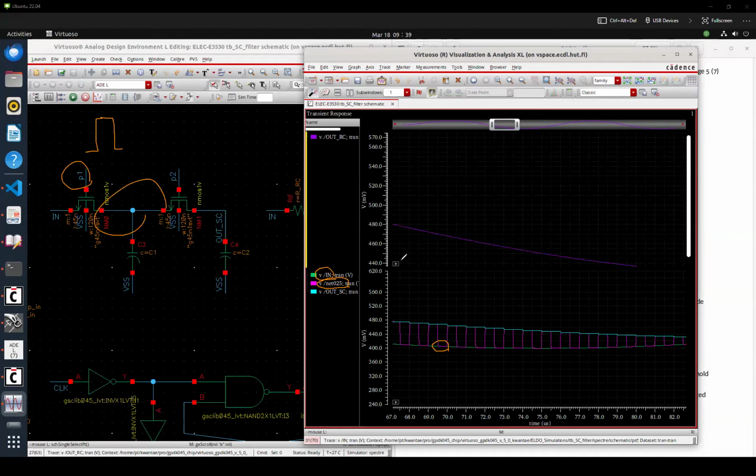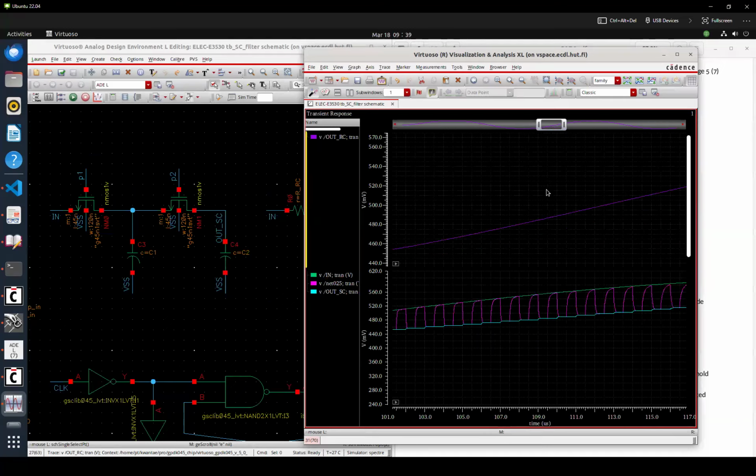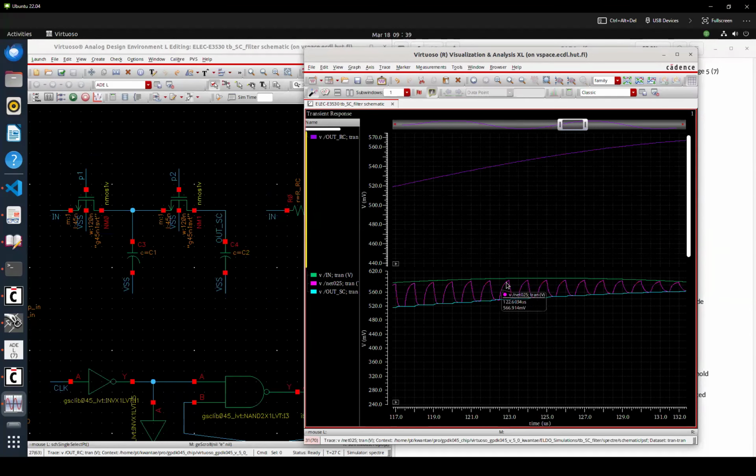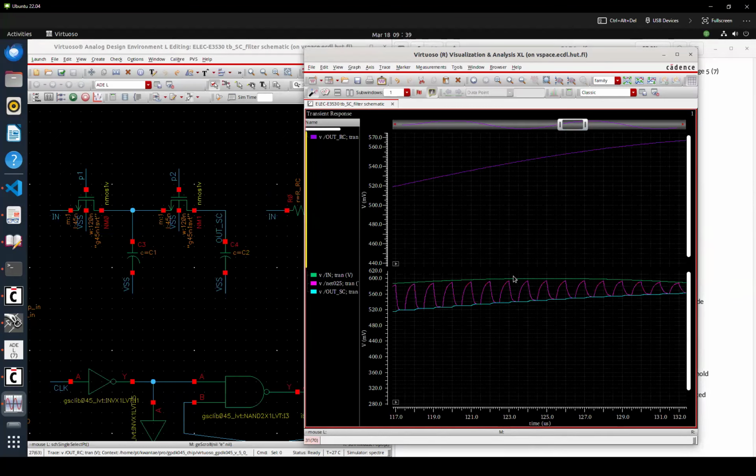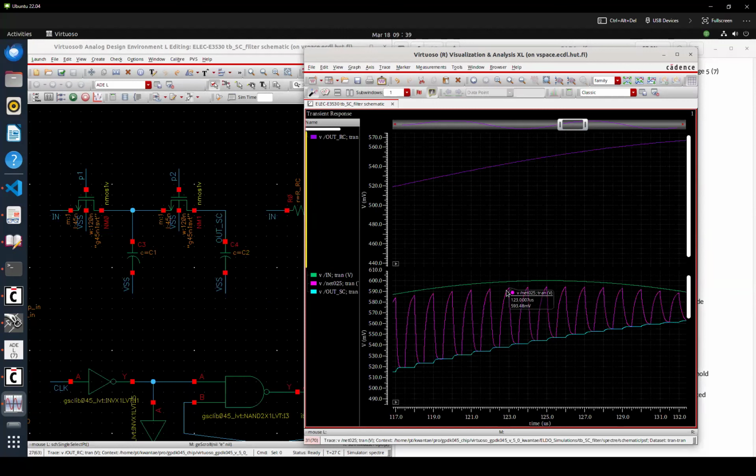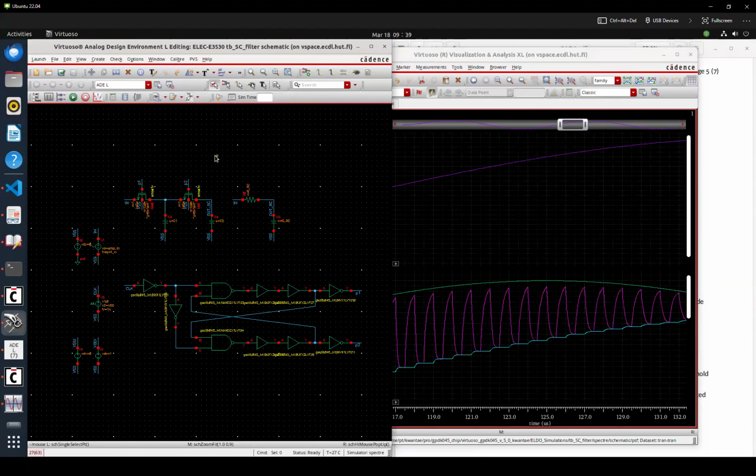When V1 is low, then it should be following V2, because V2 will be turned on after some non-overlapping time, and it should follow V_out at C quite well, right? But as we move on to higher values of V_in, you can see that it is not following quite well because of limited bandwidth. It should be touching V_in, but it's barely touching it, right? But this is a problematic situation that most of you have faced during the simulation.